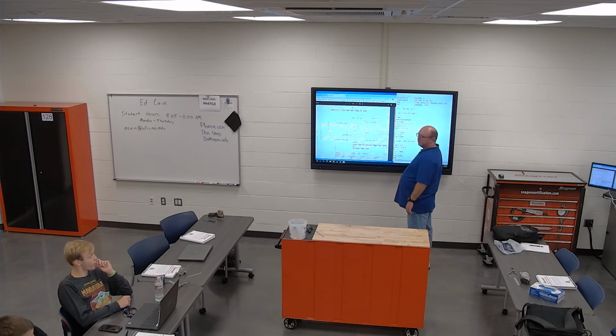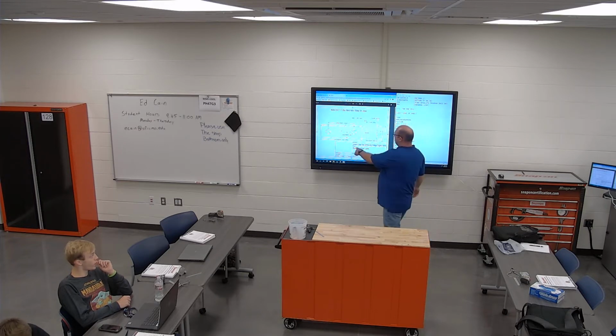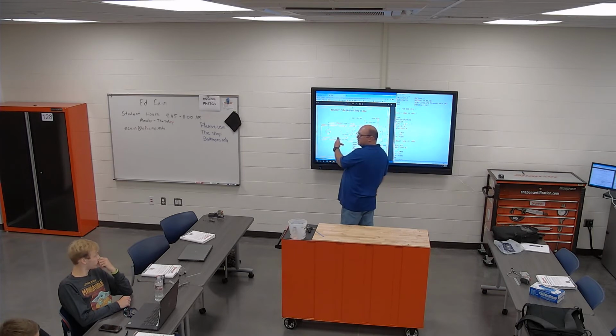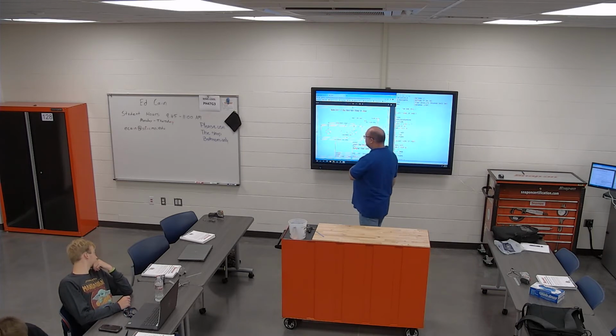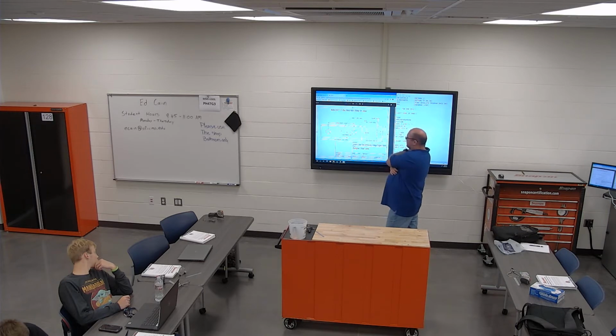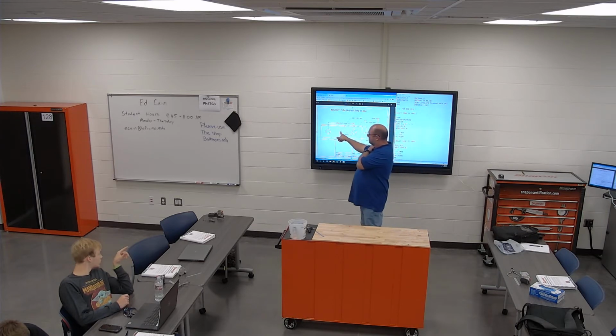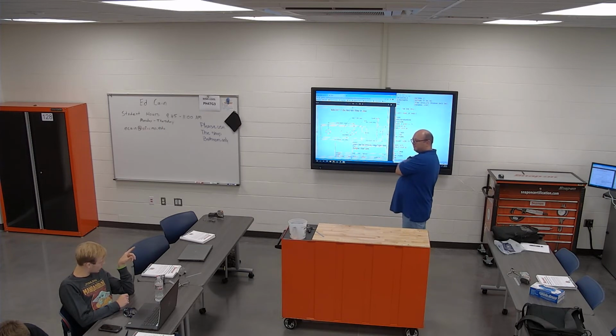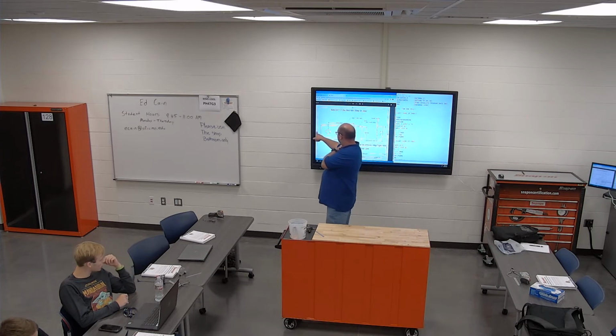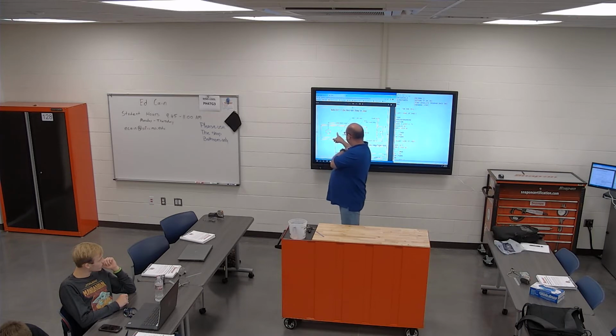So where is that, John? If this is 0, 0, and you go like this, these ways are positive. You know where this negative is? Negative 3.475 would be how far from this hole? Like, near the left side. Yeah, it's over here, right? Yeah. The way I figured that out is I went from my center line on my print to here, and then you add half the cutter to compensate for half of the radius of the cutter. So your spindle's running actually over here, which puts your mill right on the edge.